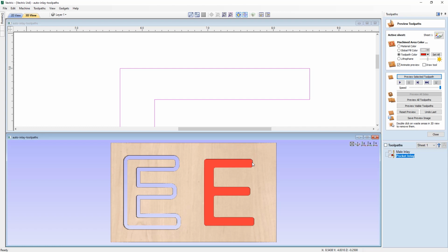So rather than cut a pocket for the female, we could look at cutting a hole and then apply a step to the male, which is pushed through from the back and locates against the stepped shelf, which is then glued together. And so you'd want to use this option if you wanted to create push-through letters, for example a sign with aluminium facing and acrylic push-through letters that could then be backlit.